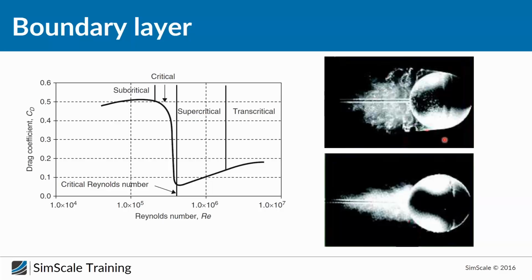Here you see a laminar separation, which is much larger and occurring much earlier. So it's separating basically, I would say, after 50% of the chord length. And with a turbulent flow, the wake structure is much more chaotic, but it's separating at a later point, I would say, after 70% of the chord length.